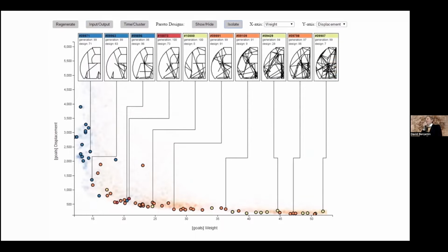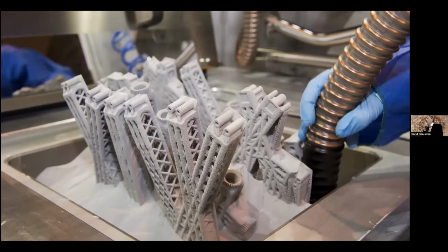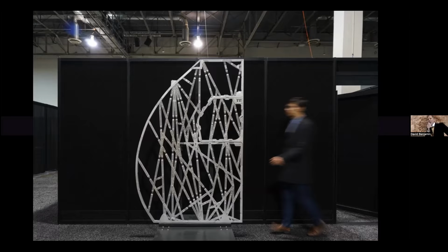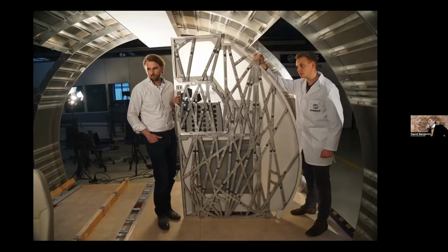So this was an idea of creating a new way of designing this airplane part. And we also wanted to test it out in the real world. So we actually built a full-scale partition. We used metal 3D printing and a new alloy that Airbus had invented for this purpose, for making low weight airplane parts. We created a full-scale partition shown here, and it's currently undergoing a bunch of certification to fly in today's A320 planes. Here it is as a kind of test fit.